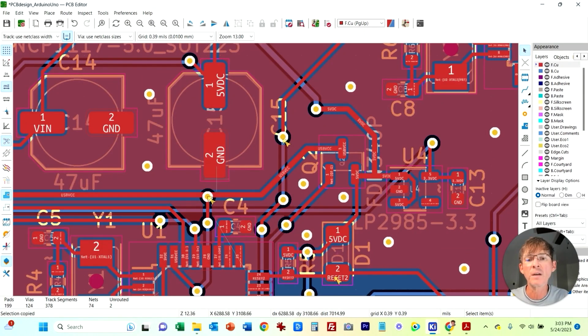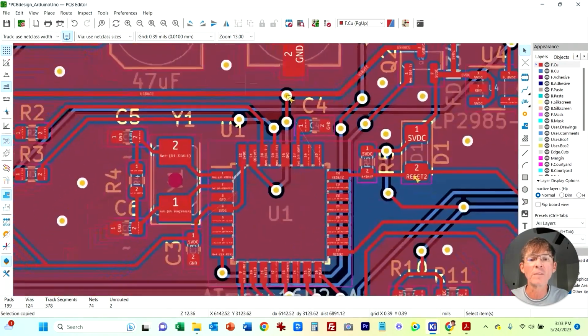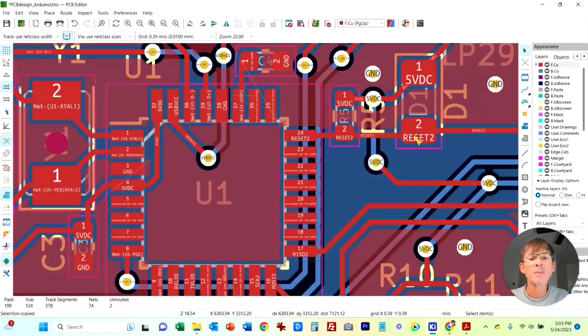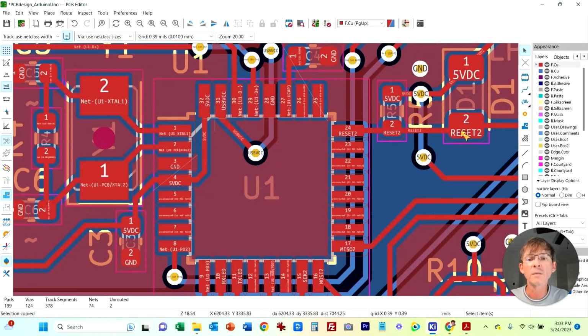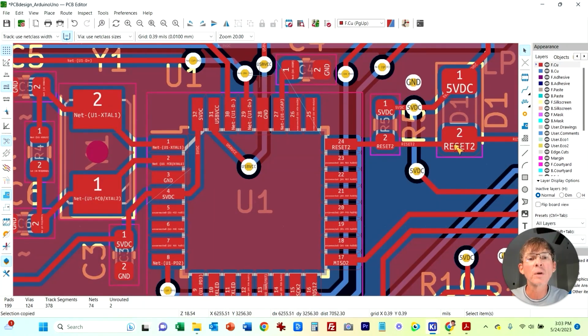See, this guy here ties into this big ground plane, so you can see it's got a via, so we know that's not it. A lot of times it tends to be the chips with higher pin counts that you can't get a ground connection out. And here are the 2 problems. You can see this ground pin here. Well, the copper pour tried to make a little copper pour here, but it doesn't go anywhere. Same with this here. This little copper pour grabs this ground pin and everything underneath the part, but it doesn't connect in with the other vias.